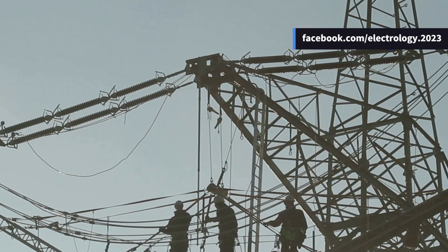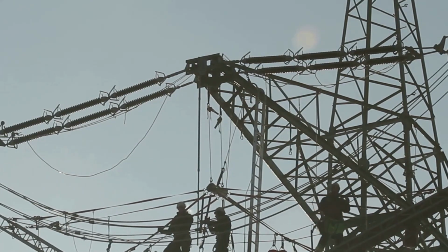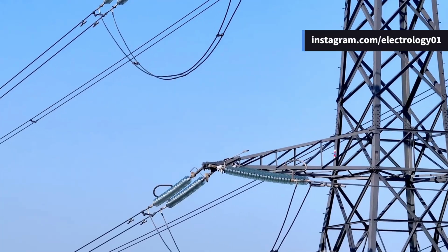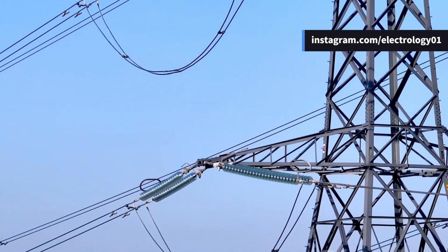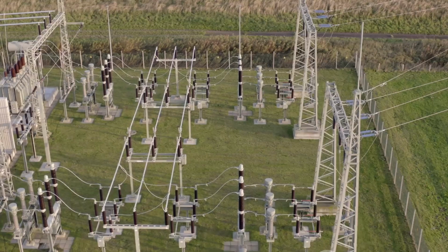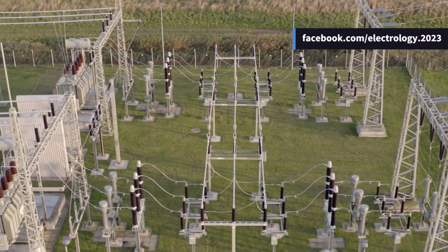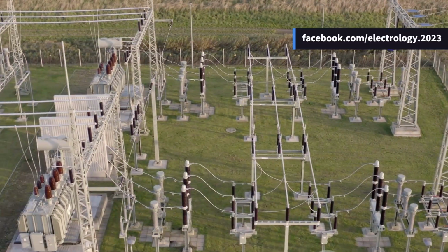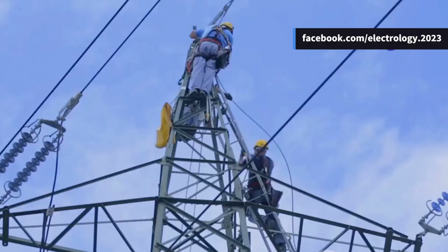And then insulation and mechanical supports. These too become more costly as voltage rises. But interestingly, the cost of conductors shows the opposite trend. As we increase transmission voltage, we need less conductor material, so that cost actually goes down. Now, when we total up all these costs, transformer, switchgear, lightning arrestor, insulation, and conductor, we get the overall cost for that particular transmission voltage.